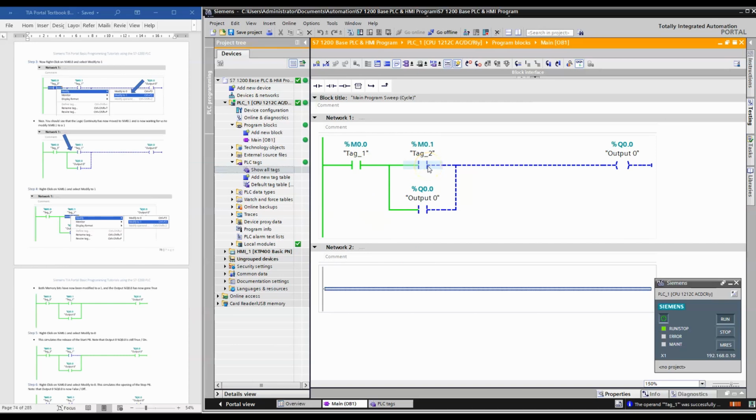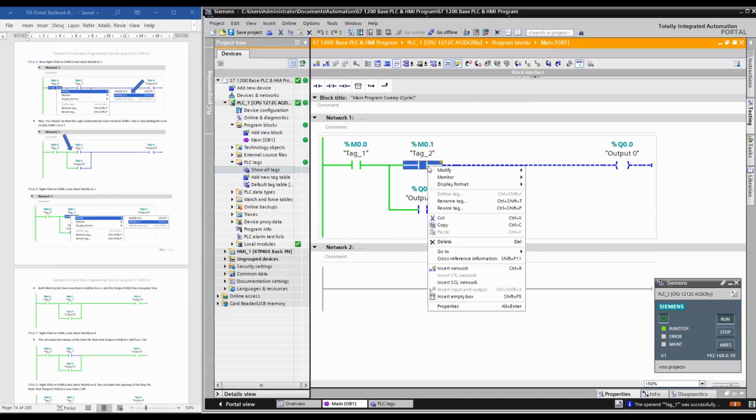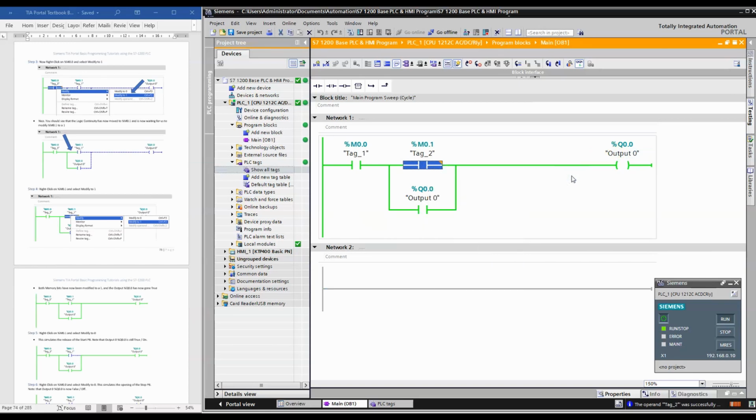Now I need somebody to physically press the start push button. So that's a physical normally open contact, which when we press would put voltage into that input terminal, and that would modify this from a 0 to a 1. So let's modify this to a 1, and we'll see that the output turns on instantly. Yes. Excellent. So now our output is on.